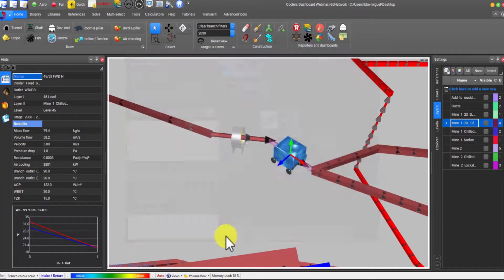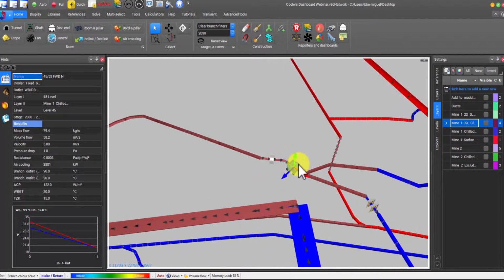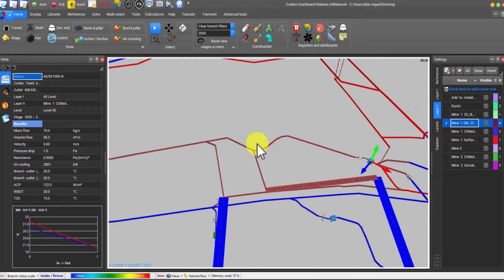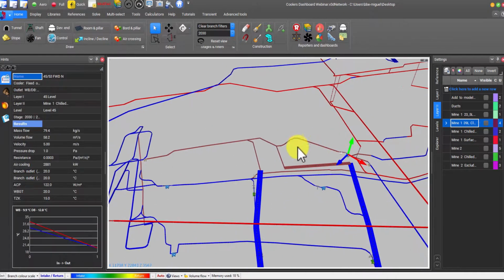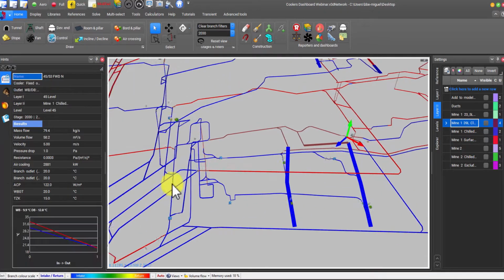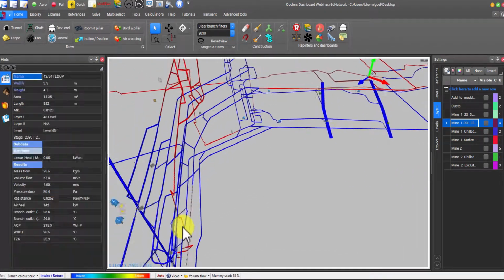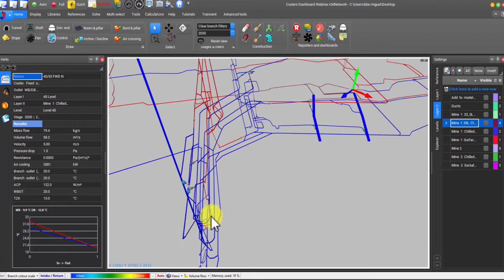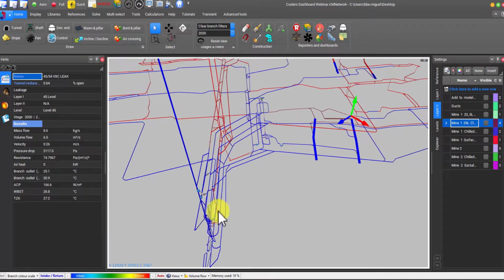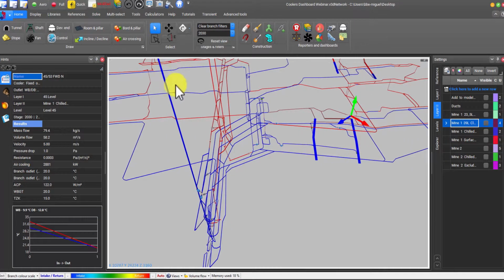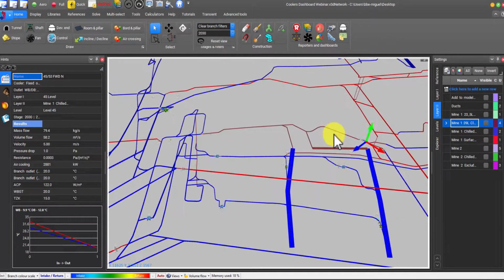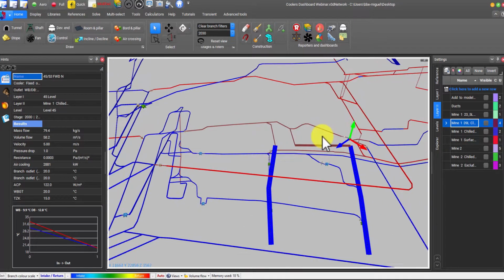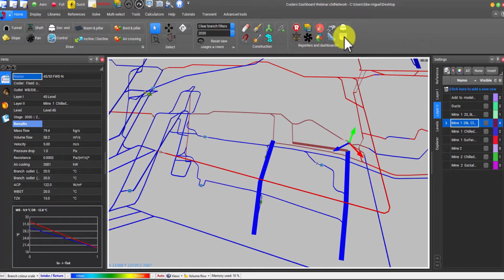Okay. It should also be noted that the 69 liters per second that is determined is at point of application. So there's still all the line losses. And you can see this has got quite a line loss because it's being supplied all the way from here, from this shaft station. And in this mine, the fridge plant sits still further up in the mine on 39 level, and that was 45 level. So always important to remember line losses.